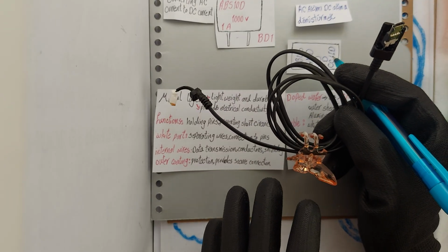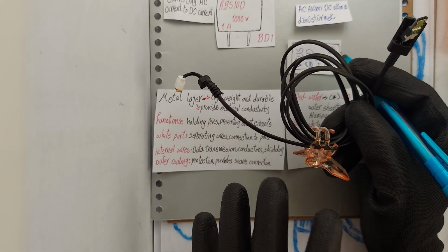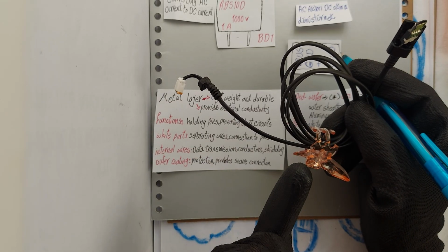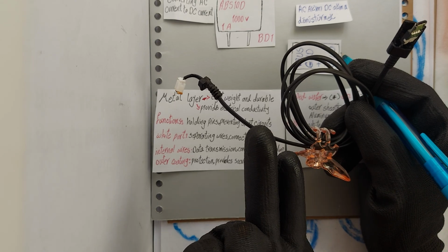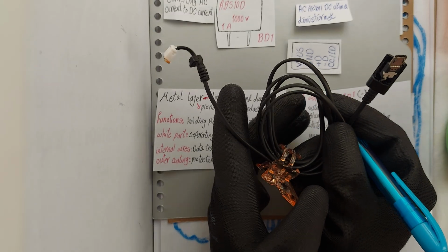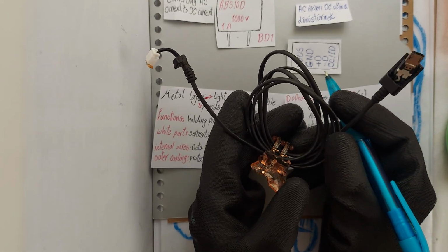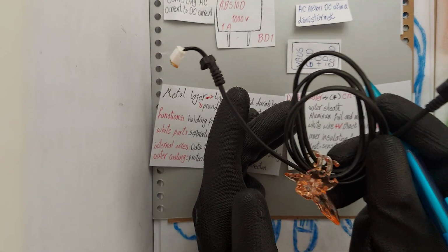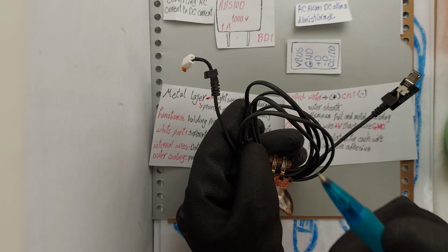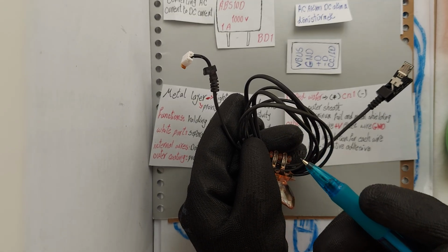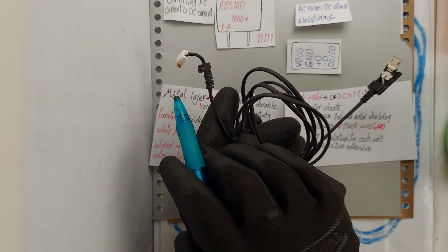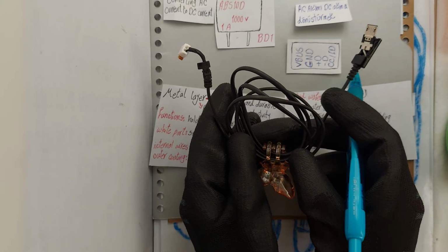And we have internal wires. Unlike standard USB cables with 4 wires, this cable has only 2 internal wires. The white wire carries positive current and the black wire, GND, serves as ground or negative. This cable is designed solely for charging devices and does not support data transfer. Insulation for each wire: each wire is covered with a thin insulating layer to prevent short circuits, and reinforcement, often a sleeve or heat shrink, is typically found at the cable's connection to the adapter or connector to prevent tearing or damage.